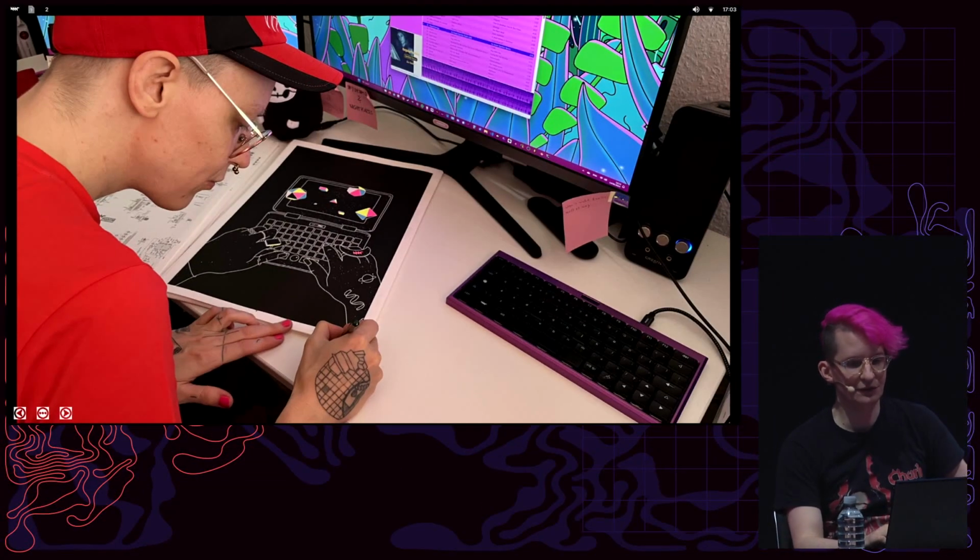Then they raised the price, so we could only get 350 instead of 500 for the price we had already paid. Then, when we finally had the displays, we realized it was very slightly thicker than the old one, and our front bezel would squeeze it and cause backlight leak. After much hair pulling, we came up with a 0.3 millimeter thick frame, laser cut from Mylar, that we can use as a gasket. The Pocket went on to be much more successful and beloved than I ever thought, so it totally saved us.